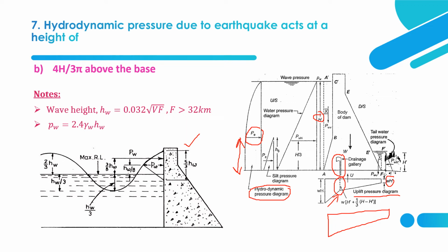So this is one of the forces acting on the gravity dam. And the most important or main pressure is the water pressure acting horizontally on the gravity dam. That is given by the horizontal component and vertical component. This is the vertical component, or vertical column, which exerts pressure over this slant surface, and the horizontal pressure is given here. That will be acting at h by 3 because this pressure distribution is hydrostatic.